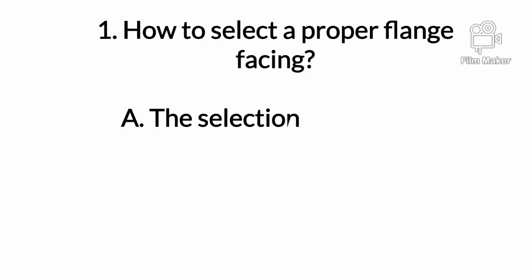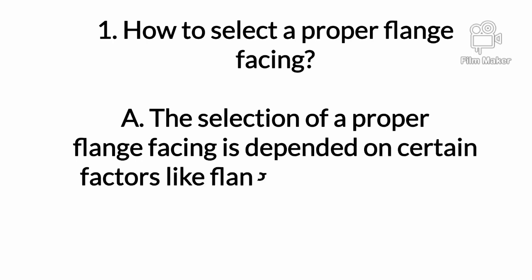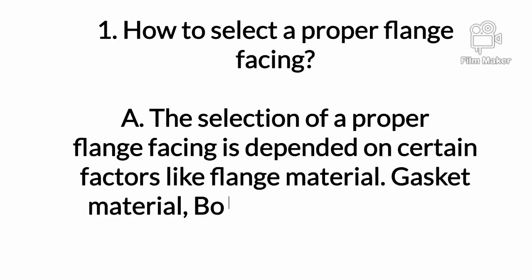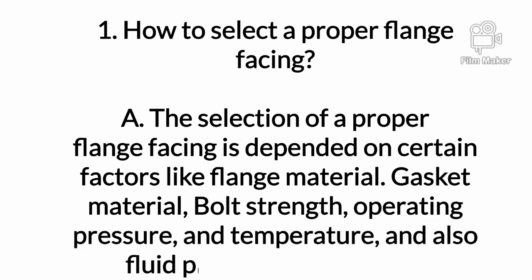1. How to select a proper flange facing? A. The selection of a proper flange facing is dependent on certain factors like flange material, gasket material, bolt strength, operating pressure, and temperature, and also the fluid properties contained.